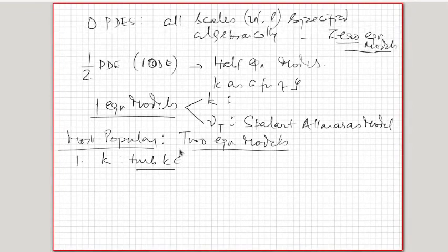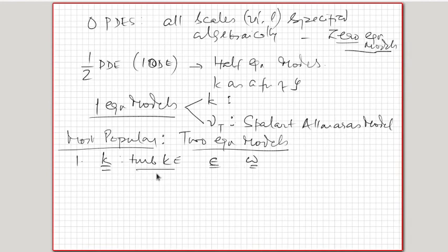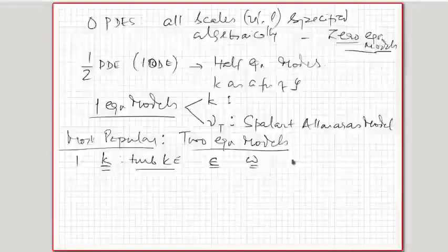in the viscous scales. So you will have a conservation equation which will have a source term for this k, that is coming out of viscous shear and buoyancy and all those terms in the mean flow, and then transportation, which is advection and diffusion of k using the advection term and diffusion term, and you will have a dissipation term in the form of epsilon or omega, which will take care of destruction of k in the viscous end below the Kolmogorov scales. So you will have a conservation equation for k, which is a PDE, and you will solve for that.